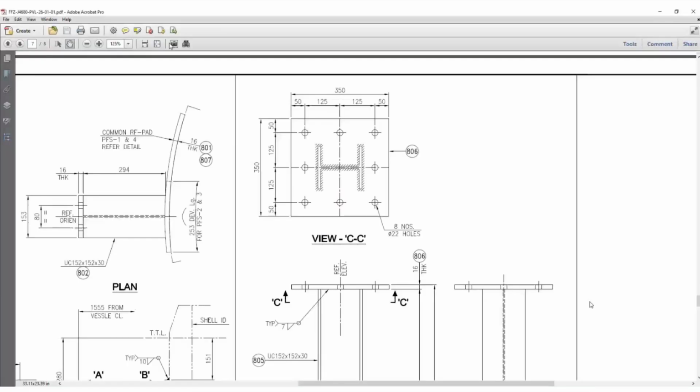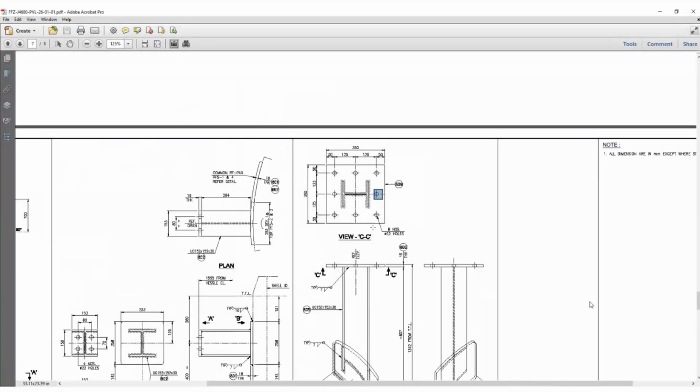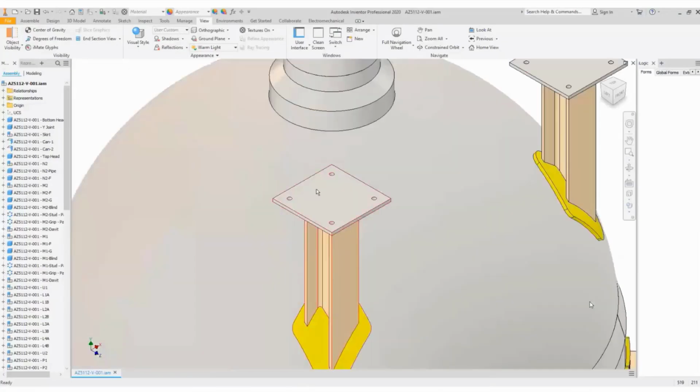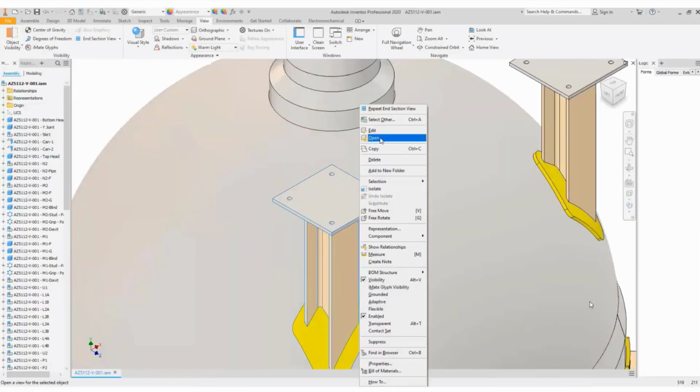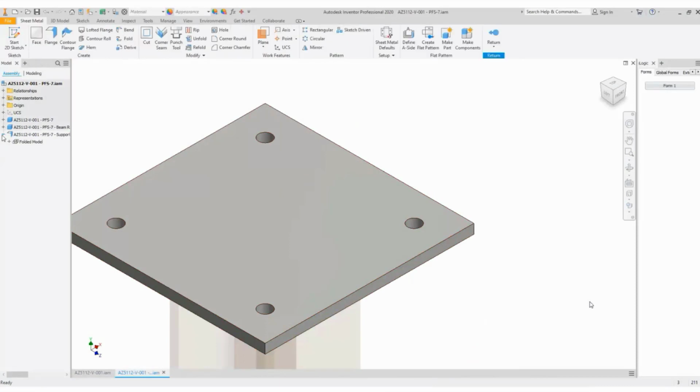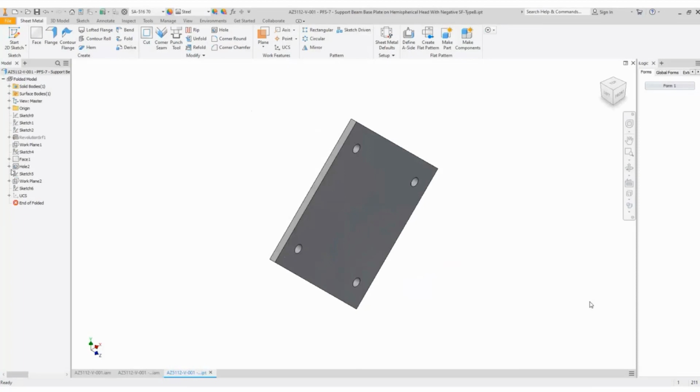Another way to modify is customization over an SEG part. For example, here in your model for the vertical vessel, we have a platform clip at the top of the head. Okay, and actually in SEG software, this end plate includes 4 holes only. The option is for 4 holes, not for 8 holes.